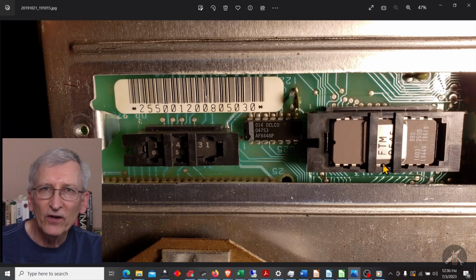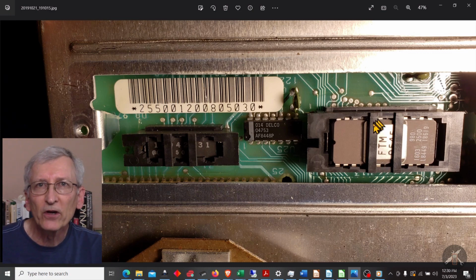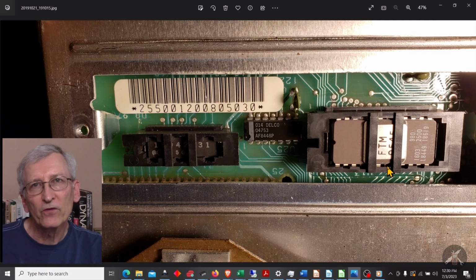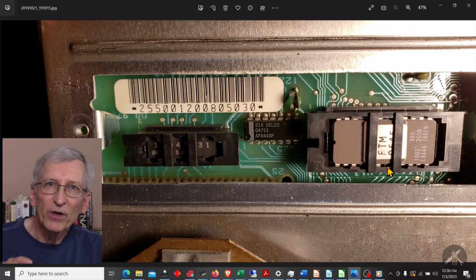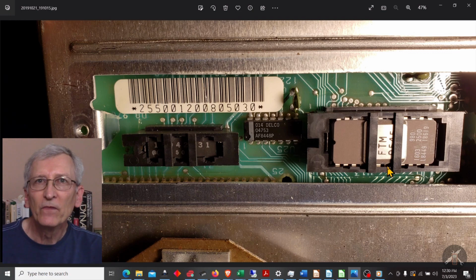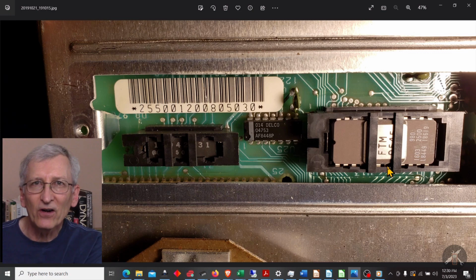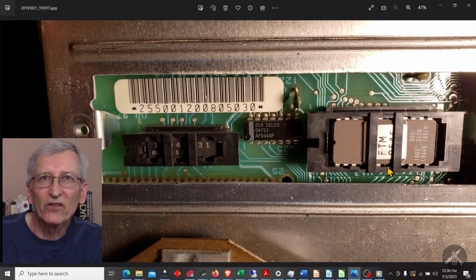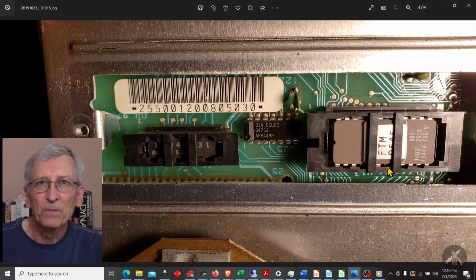The only thing that identifies the different calibration chip, to make it easy, is usually a 3 or 4 letter broadcast code. I don't think I've seen a 5, but normally it's 3 or 4 letters. It tells the guy on the line what part to pick out of the bin and put in. When you're in a vehicle assembly plant, there will be a broadcast code on the ECM, FTM, and when the build sheet for the car comes down the line, an assembler has to pick an ECM out of the rack and plug it into the car, they'll be looking for that broadcast code.